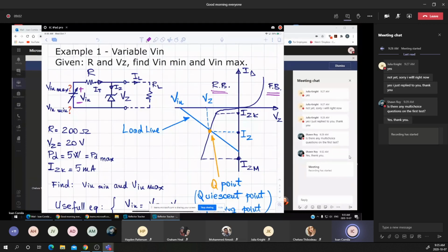Suppose that I have a circuit that is already supplied by 20 volts, but a sub-circuit or an extra device is required to have just 10 volts. Do you need an extra rectifier? Probably not. The easiest way to make 10 volts available from a 20 volt power supply is to use a Zener diode. That's the voltage VZ.